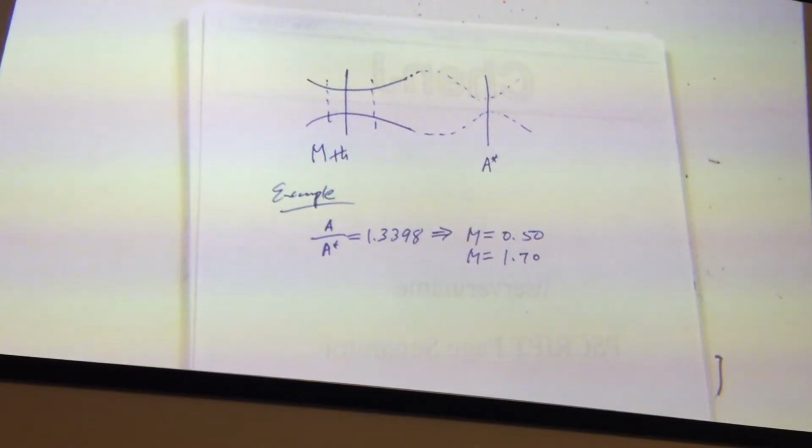Now, let me digress a little bit. Stagnation pressure is a very important concept because that's the total pressure you will have. Right? So in an isentropic flow, again, that stagnation pressure is the same throughout the flow.